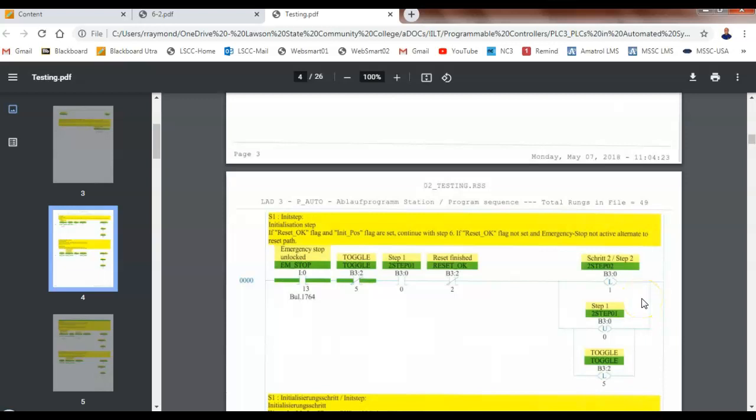So let's say we're dealing with a double acting cylinder. We've got to energize this cylinder to move it that way. And then when it hits the limit switch, we might want to automatically do what? Swing it back. So the first time we'd latch it would cause it to swing this way, and when that sensor triggers, we'd automatically do what? Bring it back. Okay, that's just one example that I could think of.